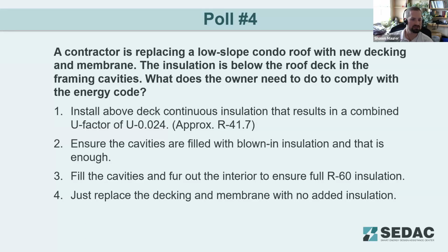Let's share those results. So the correct answer here was, since this is roof insulation that's in a cavity, all you have to do when you expose that cavity is fill the cavity with insulation. So answer number 2 here was the correct answer. The others don't apply in this particular situation because it's cavity insulation in the roof, like a cathedral ceiling, let's say.